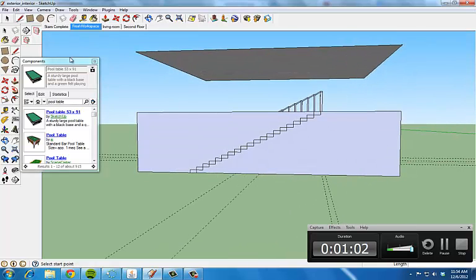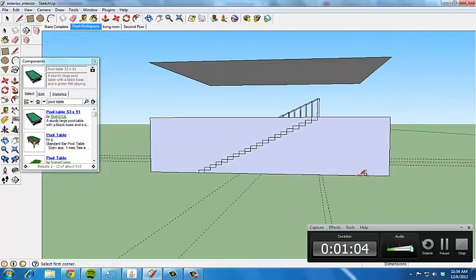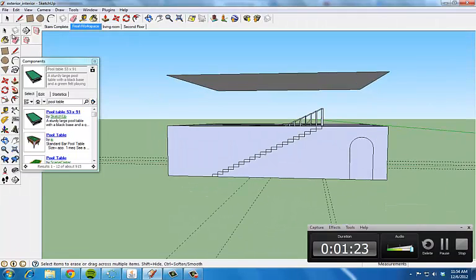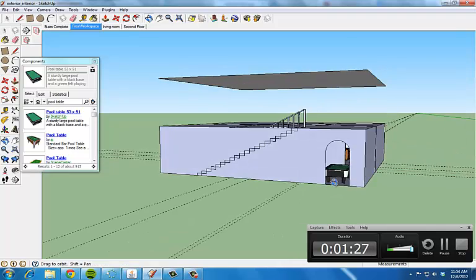So let's go ahead and just make a simple opening. I'm not going to worry about it as having a big ornate front door. I'll make it the same size though, 4 feet by 6 feet with an arc of 2 feet. But since the actual outer walls aren't 6 inches thick like the inner walls, I'm just going to go ahead and click on it and press delete.